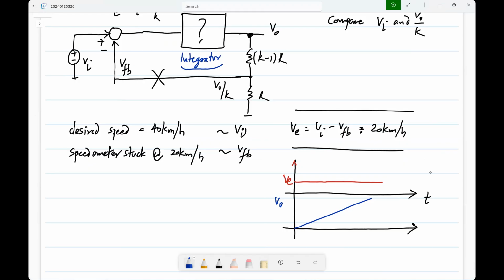So basically, what this integrator does is, as long as the input is positive, the output will go on increasing. When the input is negative, it will go on decreasing. It will stop when the input is 0. So what makes it stop is this comparison. When the result of this comparison goes to 0, that's when it stops. So that is what negative feedback is. Is this okay?